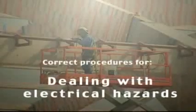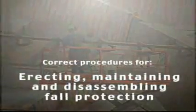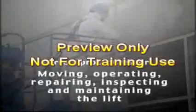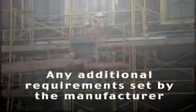Training should include the nature of any lift hazards, electrical hazards, fall hazards and falling object hazards in the work area, the correct procedures for dealing with electrical hazards and for erecting, maintaining, and disassembling the fall protection systems and falling object protection systems being used, the correct procedures for moving, operating, repairing, inspecting, and maintaining the type of lift in question, proper use of the lift, and proper handling of the materials on the lift, the maximum intended load and the load carrying capacity of the lift used, and any additional requirements set by the manufacturer.